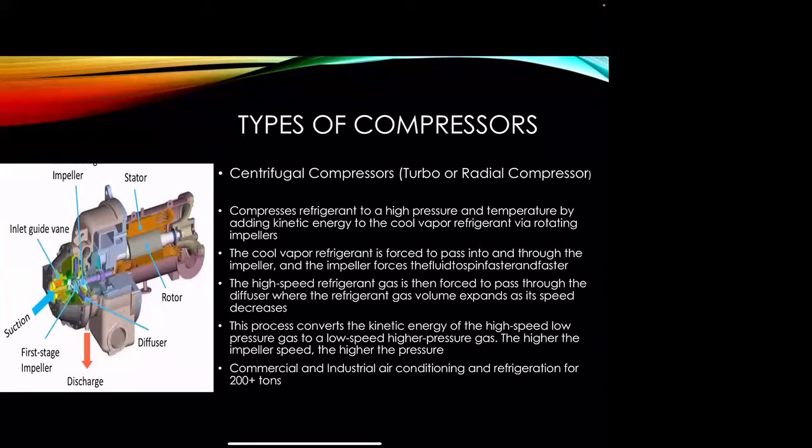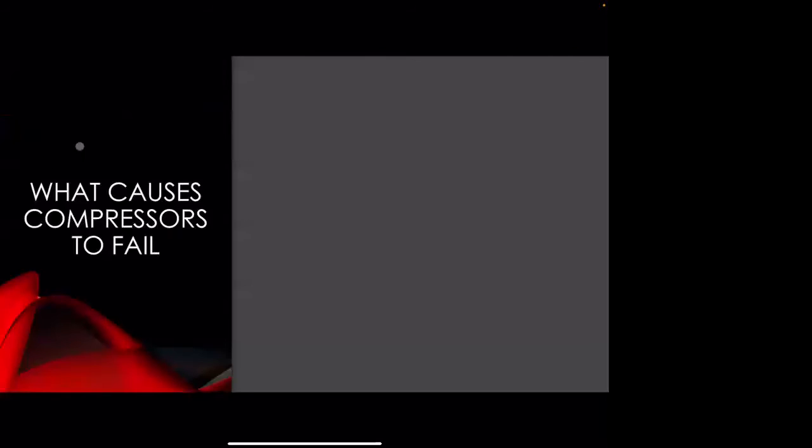Now, as we went through all of those, you may have seen that, again, it's going from a low pressure vapor to a high pressure liquid or heated up. So what causes these compressors to fail? Well, lubrication or lack thereof.